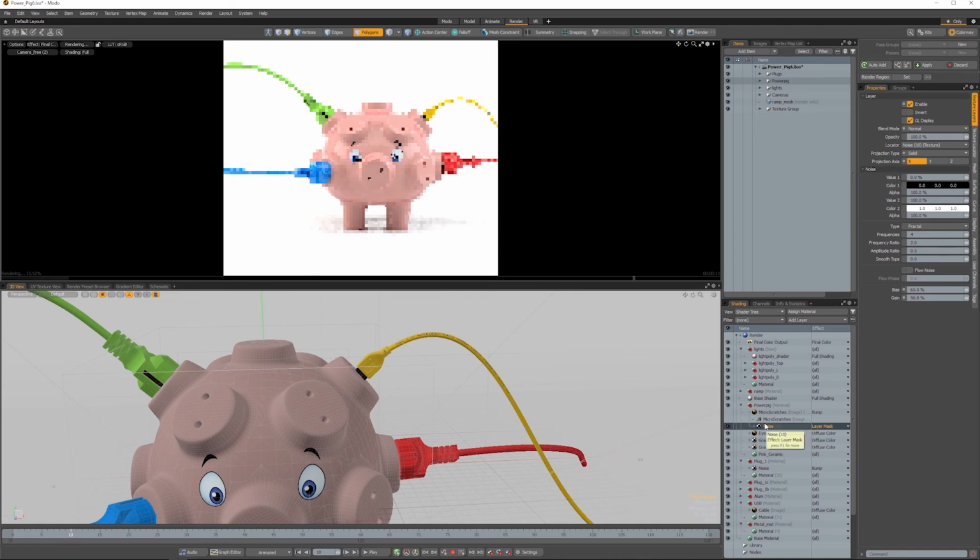And if you want to visualize it, you should select it, come here, current layer overlay, and let me jump again. And okay, I have to activate it, I think. So you see these red areas, those are the points where you'll see the scratches showing. So if you want fewer scratches, you just have to increase here the bias to 70%, for example. So you'll see that the red areas will reduce. So it means fewer scratches. Okay, I'll just leave it at 65 again.